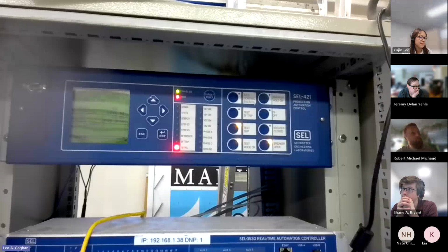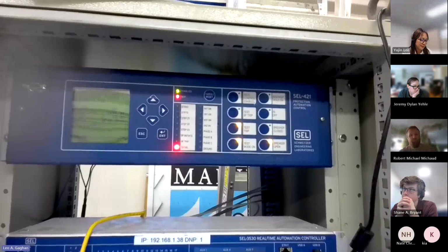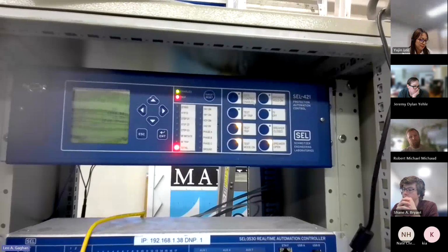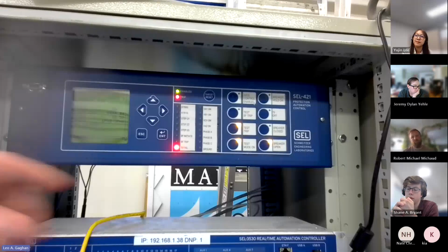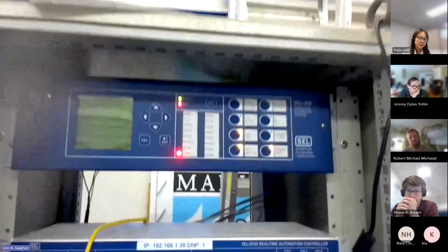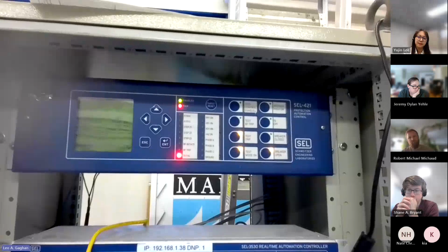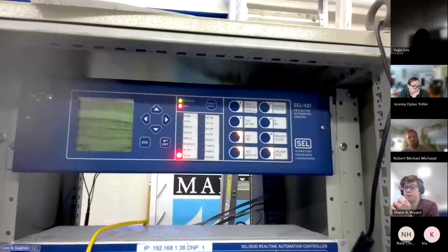We don't want to reclose because it's failed, right? So rather than allow us to reclose, it just drives that whole thing to lockout. Rather than going through that whole sequence, we would have just gone straight to 79 lockout. You also could have gone through it, trying to see, does it work with 79 off?